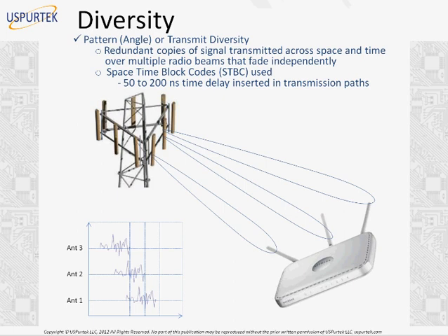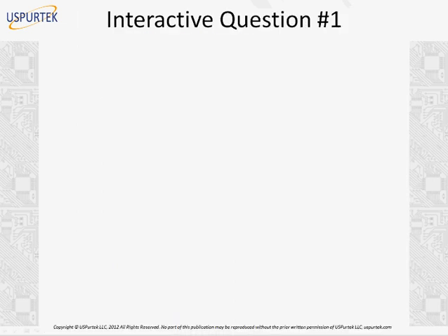Polarization diversity is inherently implemented in circular polarization. This we have seen in the previous webinar too. So the idea here was to highlight that fact. So we definitely have diversity inherently implemented in circular polarization. Our cellular systems, if they could implement circular polarization in their cell towers, then on the handset, if you lose the vertical component but you still have the horizontal component, your fading effects will be reduced. Very good.